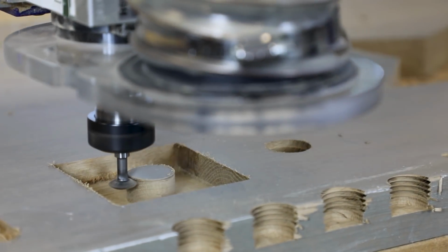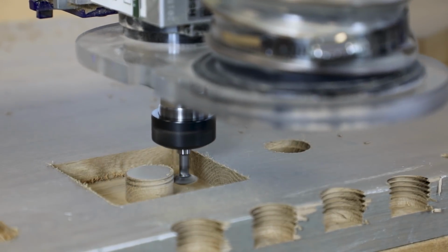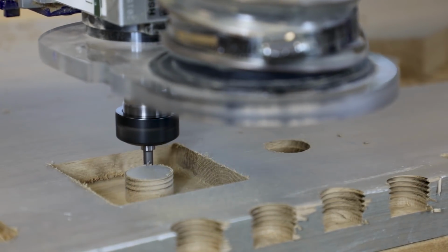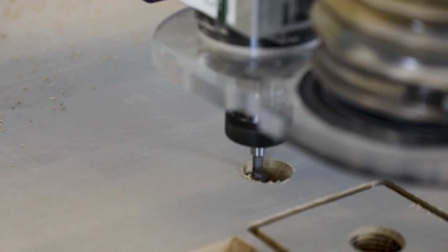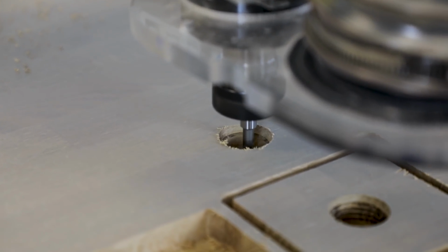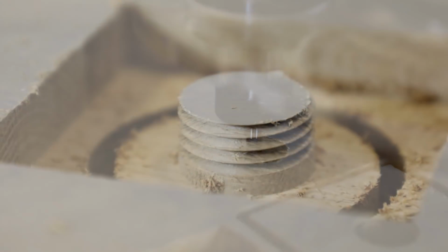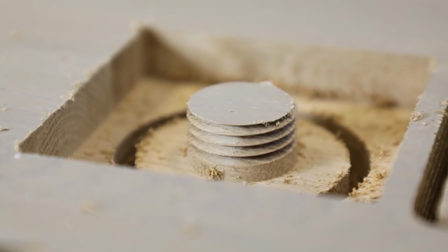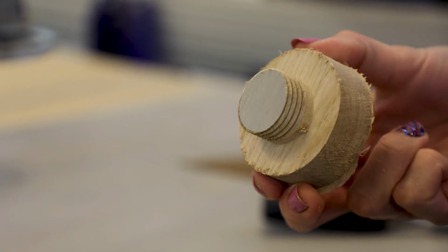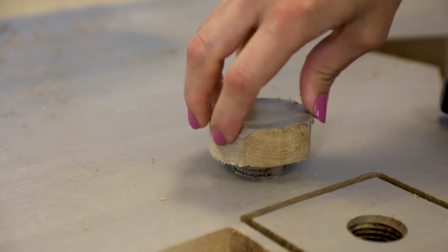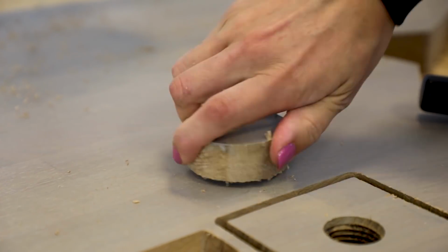This is a detailed overview of the thread milling toolpath strategy, where we're going to look at all of the options in the form to show you the effects of the different settings that you have on the toolpaths that you create. The thread milling toolpath enables you to machine internal threads to create a hole that you can screw a threaded bolt into, and you can create external threads for the exterior of a bolt, where it does this using specialist tools and a helical toolpath.